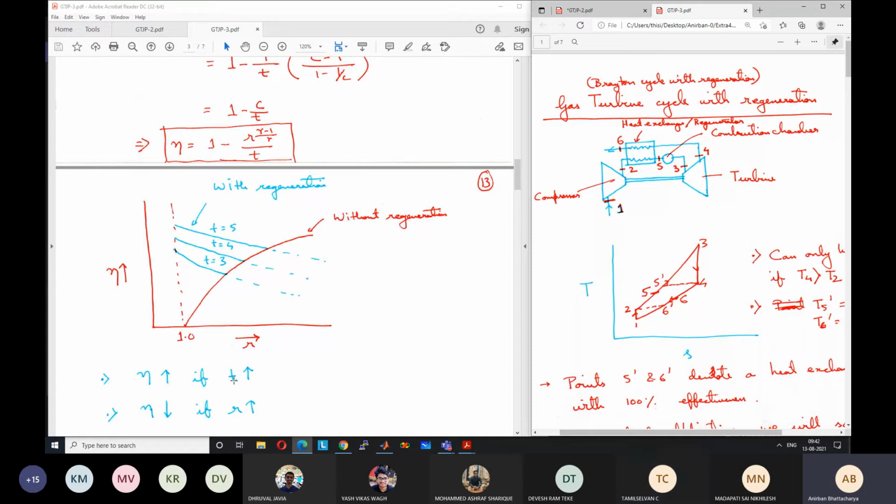It was not the case for the Brayton cycle. So what has happened there? Because the scope for regeneration, the temperature difference between T2 and T4, is increasing, sir. Correct. Because your T3 point goes higher and T2 minus T1 remains the same. So T2 is at the same height. R is fixed and T3 goes higher, which means T4 also goes higher. So the difference between T4 and T2 increases, so the scope for regeneration increases. So with increasing T, you get higher regeneration.